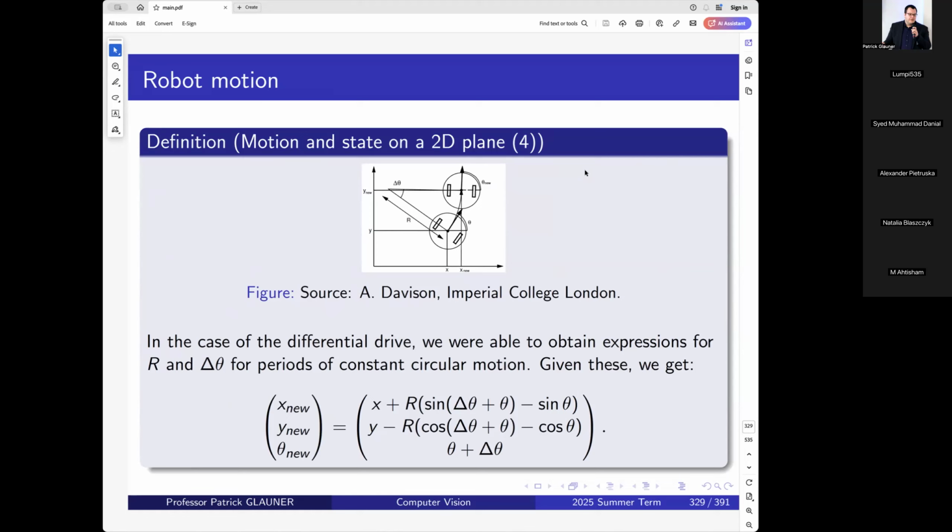So you don't need to turn explicitly and then drive straight, but rather drive from your location up to here, using this differential drive by using different velocities. And then you could have this circular drive. You can update X, Y, and theta by using some of the geometry we had before, where we said our delta theta is the angle that we are turning, and we want to plug this in, and you can derive something like this.